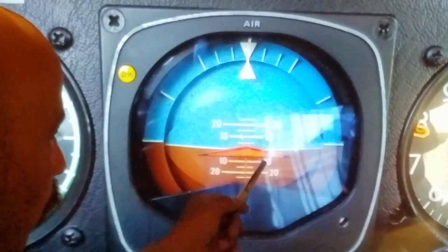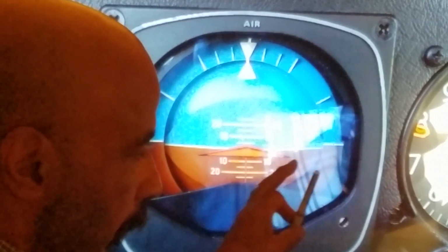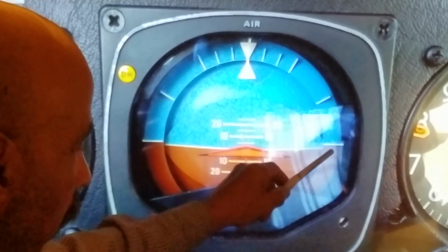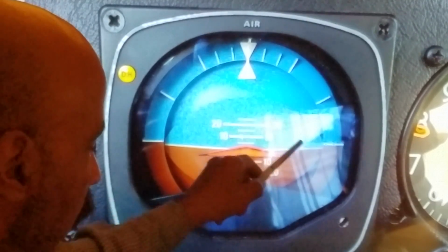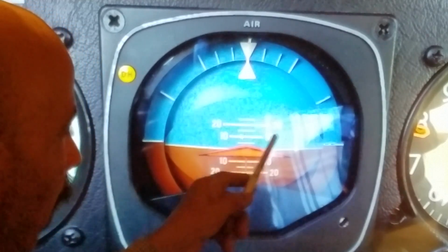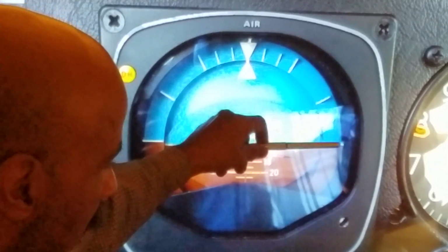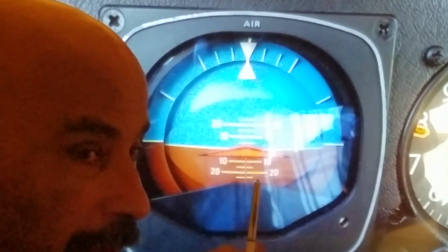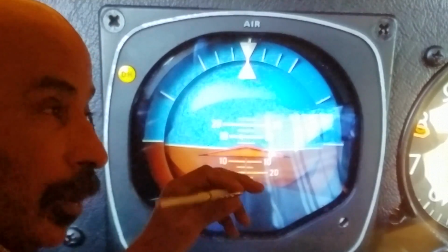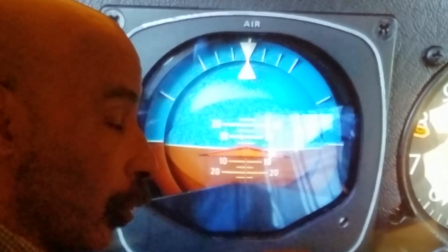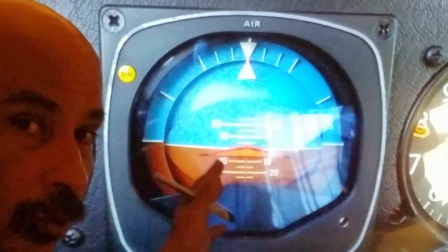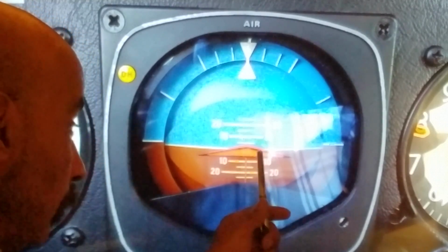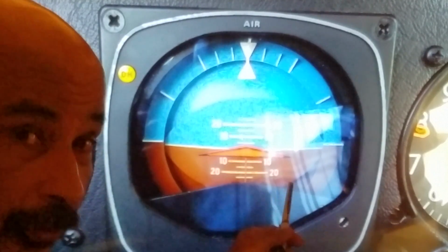Right now it shows an indication, and because the aircraft is not running, this indication is not accurate. And this bar here would typically be matched with the horizon bar, and that is a 90-degree bank bar on the index here. This is a gyroscopic instrument. It uses pneumatics, a vacuum pump or sometimes even a pressure pump, to spin the gyroscope that's in this gauge. This particular attitude indicator does have the characteristics of a flight director.